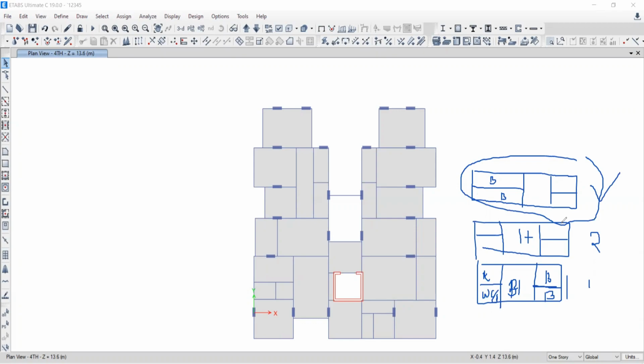Yes, sir, understood. If the architectural arrangement at the different floors is the same, then we can call them typical floors. First, second, and third are exactly the same: the position of bedroom, hall, kitchen, everything is the same, so these three floors are typical. When you go to the fourth floor, suppose there is a part terrace, so it becomes different from the lower three floors. If the architectural plan is the same, there is a possibility that the structural framing plan will be the same.